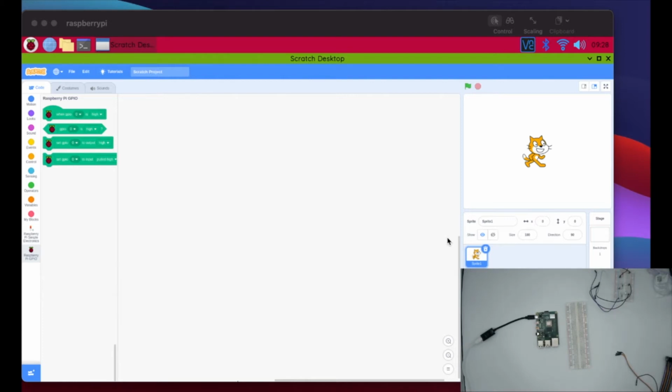So I'm going to go ahead and I'm going to plug this in now. I'm just going to plug this in, if you want to follow along, on 10, and I think it takes me from 10 and then looks like 11, 10, and 13. So there's a little bit of a space there. And I've got that right here, and I can see that my positive is on the top side. And we're going to do something very similar. I don't have to add wires to this, but if I needed some space, I could add some male to female wires and have that buzzer sit out further.